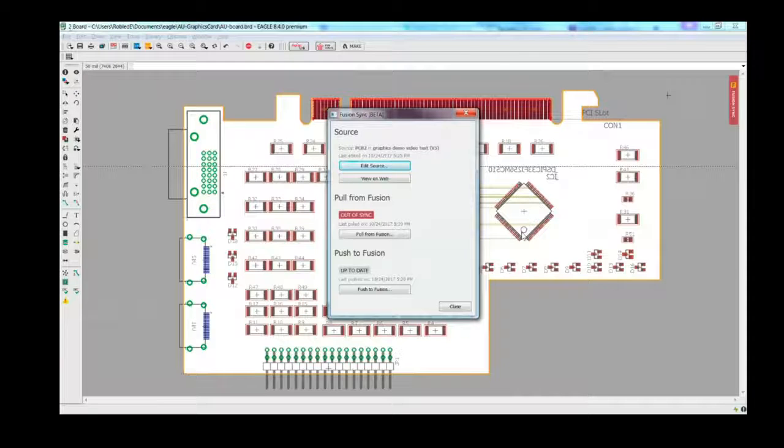Can you communicate restriction areas to the ECAD for controlling the height? In Eagle, we don't see it yet. No, not really, not the height. So that would be something they would need to collaborate on when they're pushing and pulling and making the commentary. While they do the push and pull, they would have to let us know what commentary, that way we could actually use the right component according to the height. Now we use 3D models, usually based on the manufacturer, so we do our best to get as accurate a height as possible. That way you could get enclosure violations if necessary.